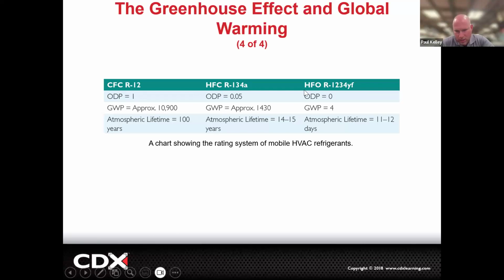There's a whole history on that, and we'll cover it. It dropped the ozone depletion potential from 0.05 to 0. He called it splitting hairs, and I can see where he's coming from. In ozone depletion that's a great improvement, but we were already pretty low. You were paying $1, then we got it down to 5 cents, and now it's 0 cents. The bigger change was R12 to R134a.